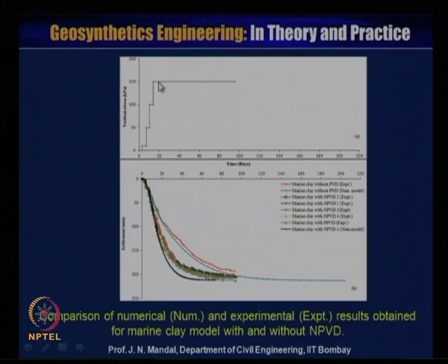You can see that earlier also it has been shown like this, the vertical stress with time, and here you can see the settlement for the different natural prefabricated vertical drains and polyester prefabricated vertical drain, and also the marine clay without prefabricated vertical drain. You can see that the nature of the curve is like this. With the passage of time it stabilizes.